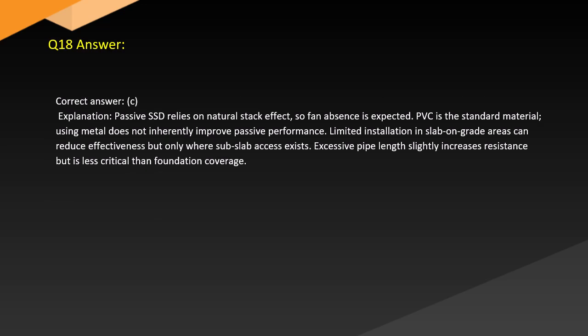Answer. Correct answer, C. Explanation. Passive SSD relies on natural stack effect, so fan absence is expected. PVC is the standard material. Using metal does not inherently improve passive performance. Limited installation in slab-on-grade areas can reduce effectiveness, but only where sub-slab access exists. Excessive pipe length slightly increases resistance, but is less critical than foundation coverage.